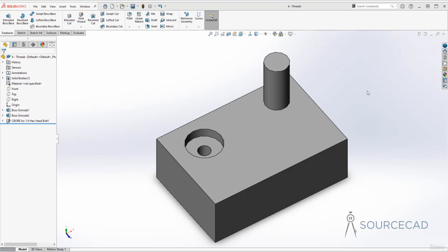the drawings. For example, in this case, if you just want to show that this shaft has a particular thread or maybe this hole has a thread, then you can do that directly in the drawing rather than adding a real thread here. The reason why we avoid adding real threads is because it's resource intensive and it consumes a lot of resources, and the drawing tends to get slow because of threads.